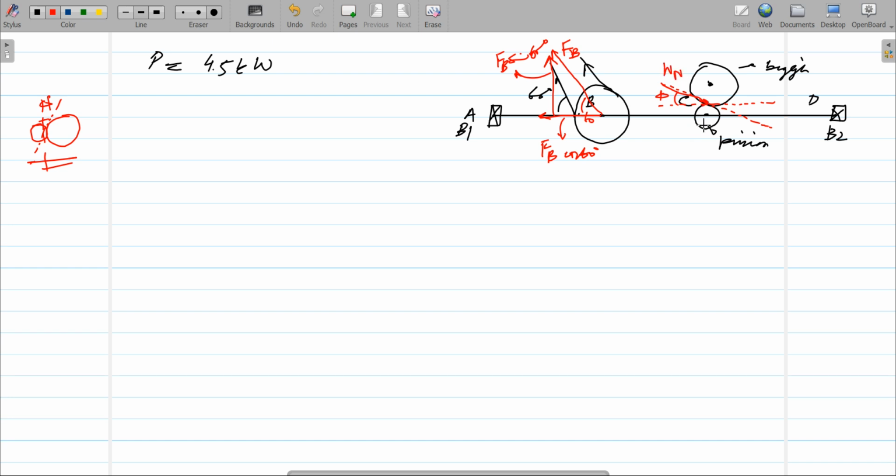It is very important to see in which direction this is moving. If you look at the figure, this is moving in the anti-clockwise direction. The gear will also move in the anti-clockwise direction. So based on this gear, the force will be in this direction. So here, this is the action gear force, WN. This direction is because of this rotation. Rotating otherwise, it would be like this. Clear?